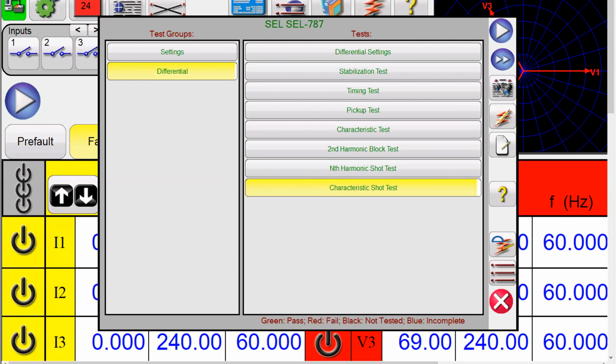For instance, you're mentioning here two IEC classifications, the 5P10 and 5P20. They are CTs that guarantee a 5% error up to 10 times the nominal secondary current in the case of the 5P10, and the 5P20 is 5% error up to 20 times the nominal secondary current. But there's no mention there, for example, of which of the, I think it's 10 classes of VAs that you have on the IEC standard.